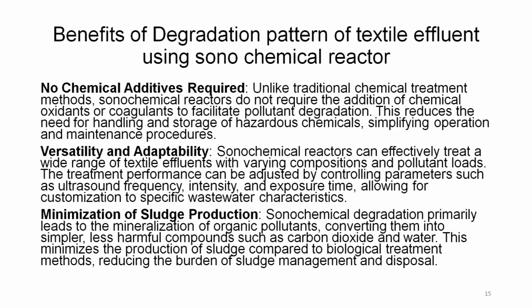Minimization of sludge production. Sonochemical degradation primarily leads to mineralization of organic pollutants, converting them into simpler, less harmful compounds such as carbon dioxide, methane and water. This minimizes the production of sludge compared to biological treatment methods, reducing the burden of sludge management and disposal. So, this also is an added advantage.